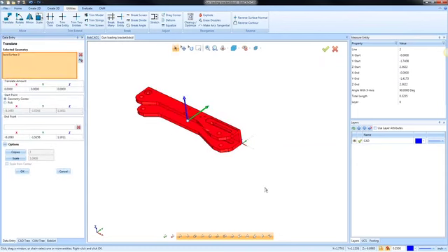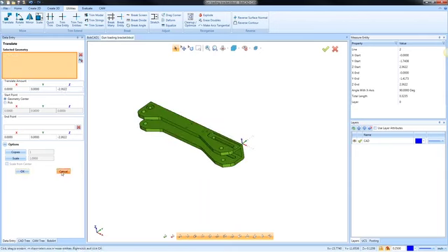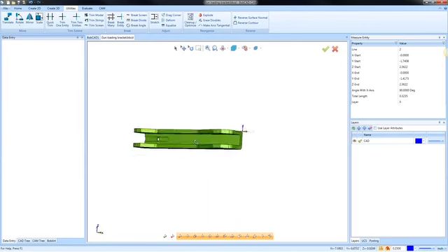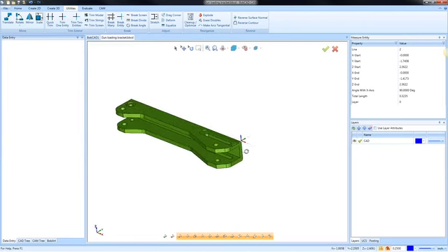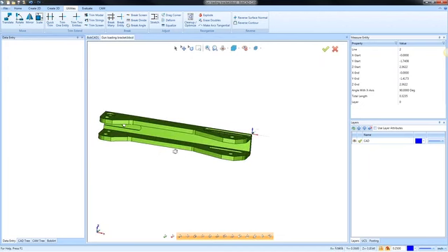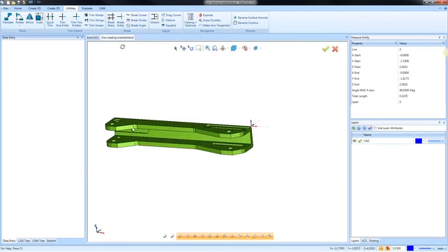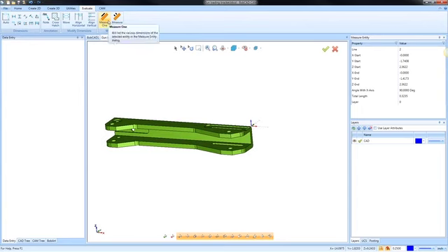I'm going to window pick all of my geometry, and I'm just going to do a delta amount. So I'll say minus 2.3622. I'll say OK, and then cancel. All right, so I've moved the part down so the top of it is at Z0. Okay, all right. So again, to find out how tall it was, I went to evaluate, measure.